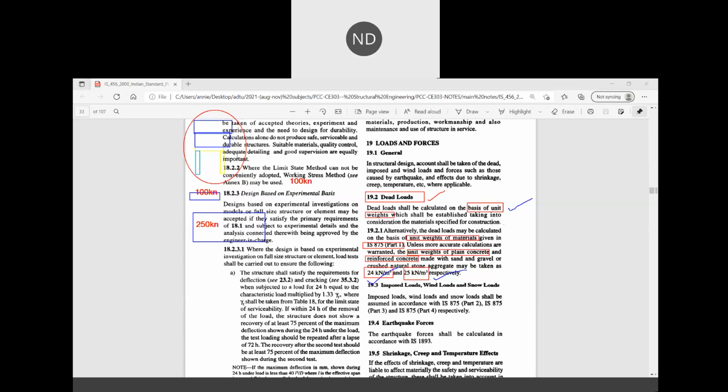So we'll make the two floors, but how can we decrease the cost? In that case, see, this one is 100 kilonewton, and this can take 250 kilonewton, right? But 100 kilonewton is, suppose, sufficient for our building. For example, I'm just telling you, if this column is strong enough to carry 100 kilonewton, which is the maximum for us, we need lesser resisting power from the beam to carry a load of, suppose, 60 kilonewton. Or suppose 80 kilonewton this beam has to carry, but it can carry 100 kilonewton. So obviously it has more resisting power, and it can be used in our structure.